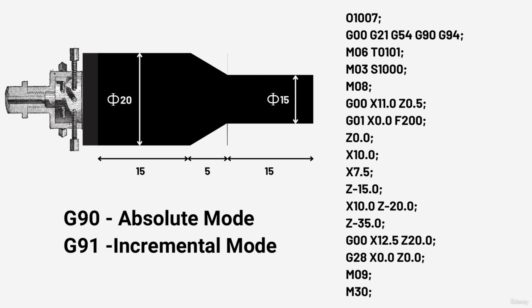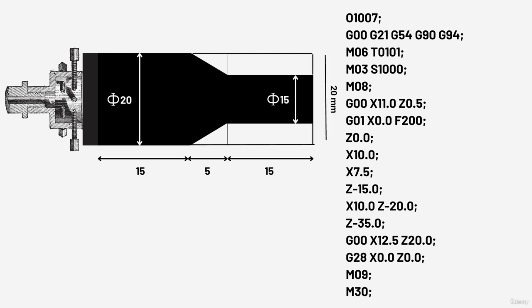We will discuss this later in the lecture, but first we need to define the size of the workpiece to undergo operation. In this case, we will need a circular bar of diameter 20 mm. This would be our workpiece. Now here we have to define a datum position from which the tool will start moving.